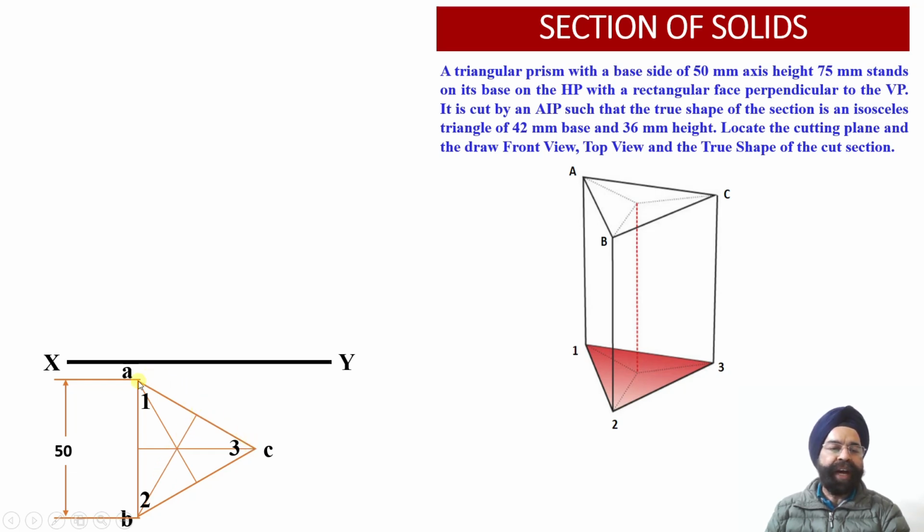Similarly, from point 1, we have obtained the perpendicular bisector of the edge 2, 3 over here. So this is the axis point corresponding to this triangular prism, that is, points O and O1 have been appropriately obtained, where O point will be lying at the top face and O1 point will be lying at the bottom face of this triangular prism.